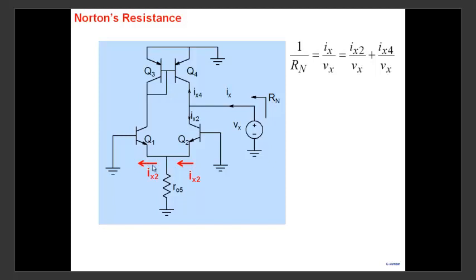Now note, please keep in mind that these are small signals. So small signals can be positive, negative and all that. Doesn't matter. So if you're worrying that how will it go up into the emitter, current is always coming down, that's DC. Okay. So small signal there's no issue with it. Now this IX2 comes here, goes up because this is the emitter current, goes up here, right? Goes up here. Now where will it flow?